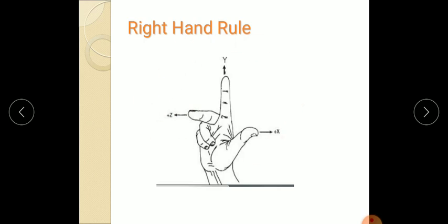All these fingers are at 90 degrees to each other, and they point in the positive directions. This represents the axis movement in the CNC machine. It indicates in which directions the movement is to be done. So this is the right hand thumb rule.